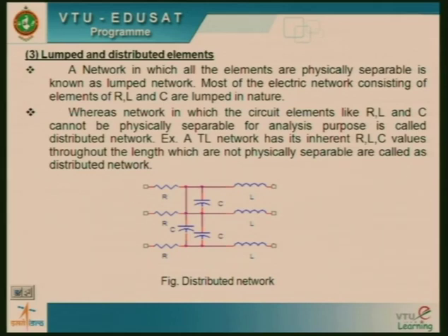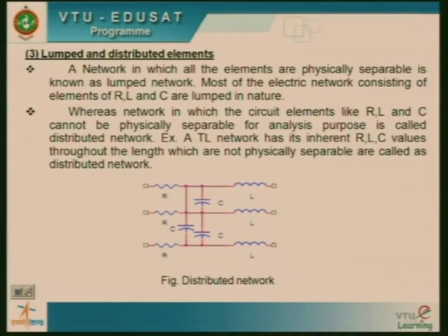If you take the example of transmission system, we will be having only the transmission lines. You can observe even outside your houses, the transmission lines running. So in a transmission line, you cannot see any physically existing resistor, inductor or capacitor. But we have as such the resistor, inductor and capacitor throughout the length of this particular line, even the distribution network or the transmission network. Transmission lines are distributed networks. You have the resistor, inductor and capacitor distributed over the length.